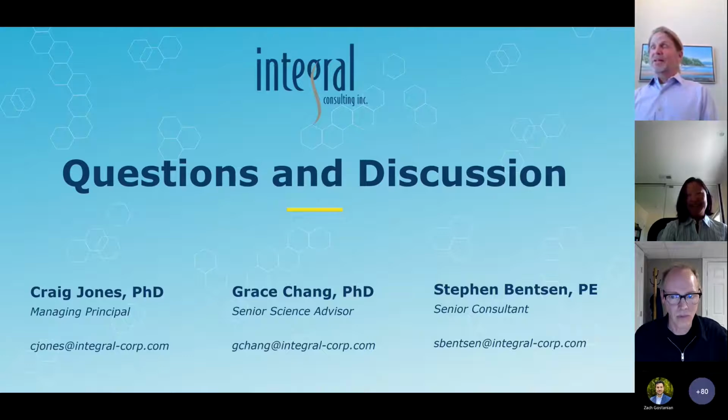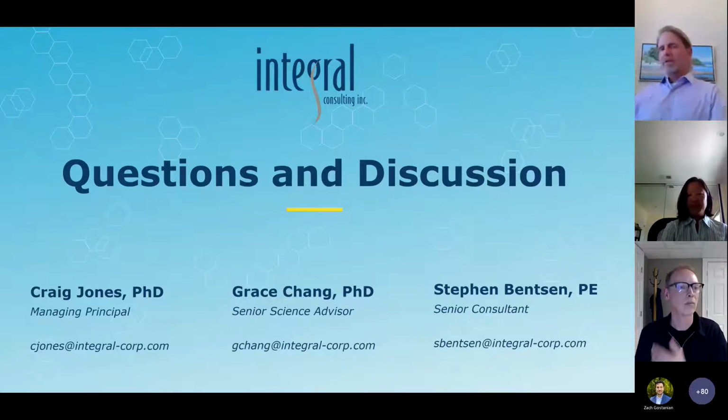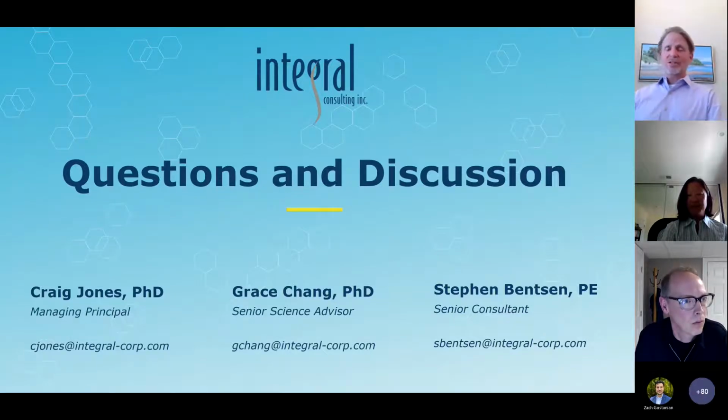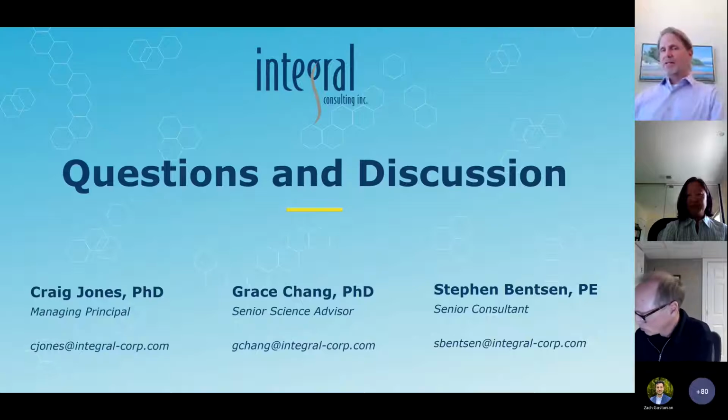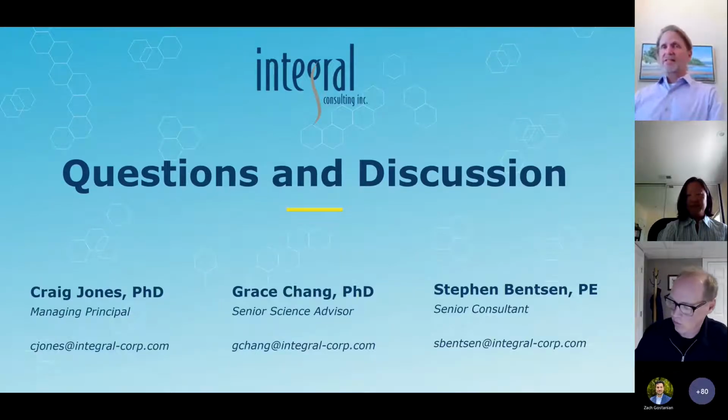That actually was an interesting site in South San Francisco Bay where we did have co-located SPI imagery, SedFlume coring, and then high resolution measurements in the water column of not only all the particle properties that Grace was talking about, but of the near bed hydrodynamics. So it's looking in very shallow areas at wave resuspension of sediment. But on shallow mud flats, you can imagine that the biota has a large effect. So it's not just the physical properties, but the biotic properties that vary significantly season to season that can influence the resuspension properties of the sediment.